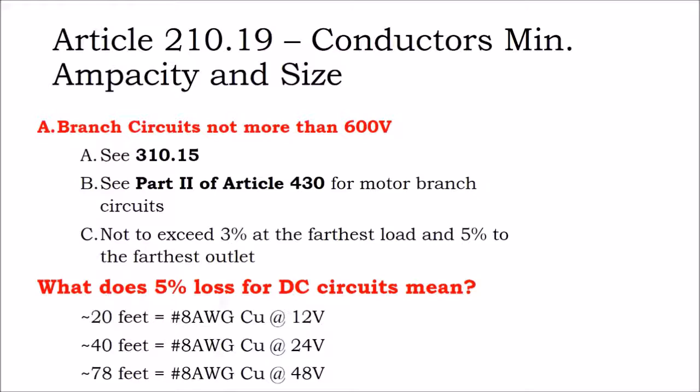It's really more to do with the low voltage of a 48-volt battery bank. We want to step that voltage up so that we can push it further. So your 120-volt circuits and your AC service panel can push electricity a lot further than a lower voltage DC circuit.